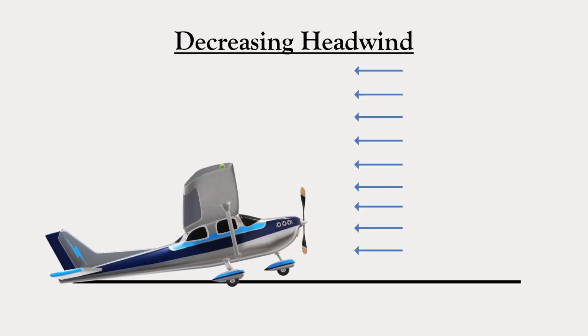Is it a big problem if the airplane wallows a while before it starts climbing? Well, not if the pilot's patient and waits for the airspeed to build up, but if the pilot panics about the failure to climb and pulls back, then the airplane may stall. If the pilot panics about the airspeed being too low and lowers the nose, then the airplane may hit the ground on the nose wheel.